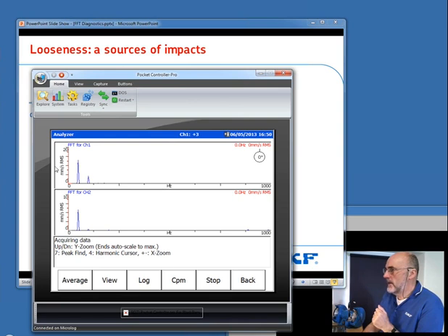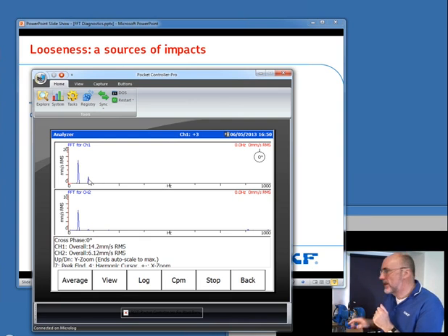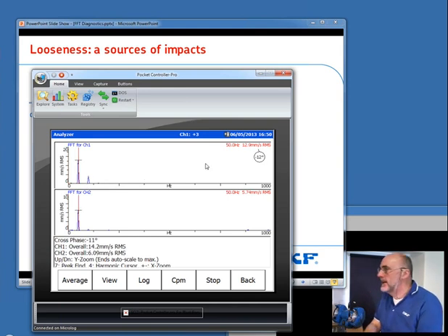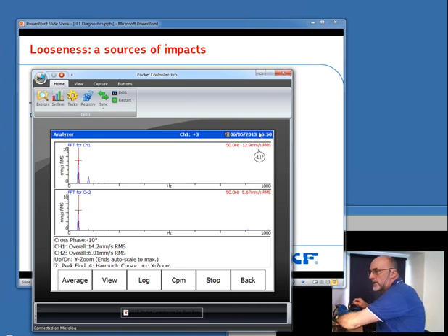So there we go. There's our vibration spectrum. There's the 2 times that we see on the tool post. I'm going to put the cursor onto the running speed. The phase is running nice and steady at 12 degrees, and the amplitude is nice and steady at 13 millimeters per second. And now what I'm going to do is just loosen the tool post.